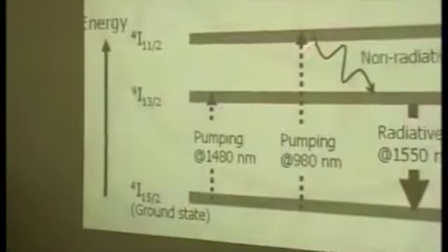1,480 nanometer laser. So in such a case, non-radiative emission transitions this higher energy state to a lower energy state. And finally, stimulated radiative emission occurs at the 1,550 nanometer band.